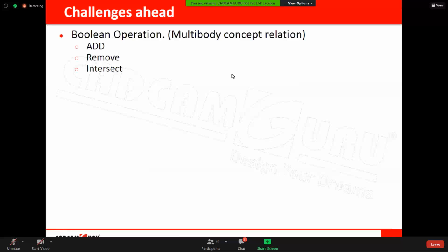We are using Boolean operations because creation of cores with Boolean operations is quite easy. You already know this in NX software. We are using a methodology there: core bodies in a separate group, and unite bodies in separate groups. So the main reason is to create casting and plastic products.